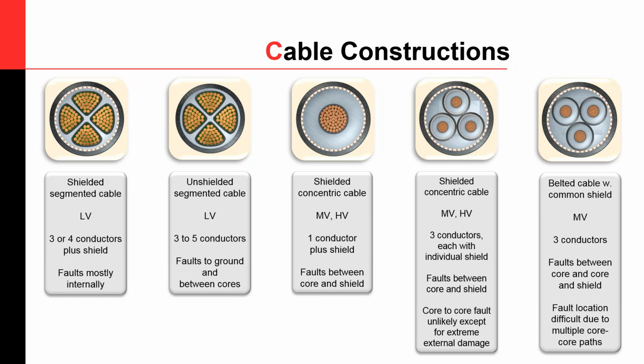And then on the right, you can see the dominant type of construction for PILC cables, from when cable installations were pretty much being conceived as electrical connections. So this is pretty much the oldest way of constructing a cable. You have three conductors, but they only have one common shield. And then that leads to certain problems.